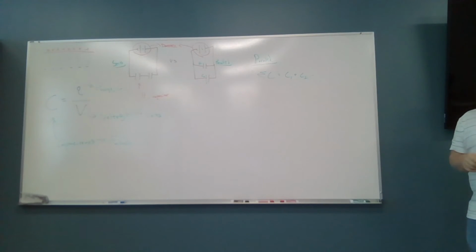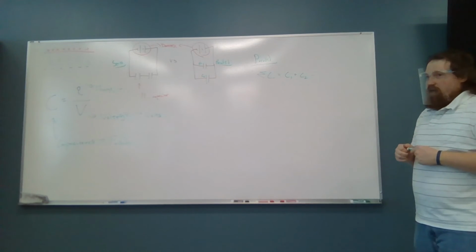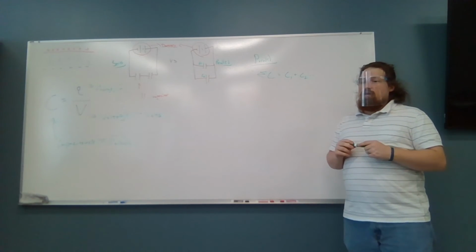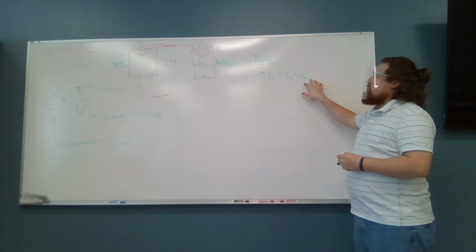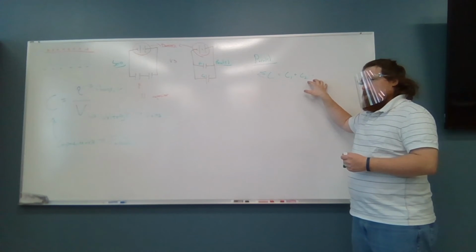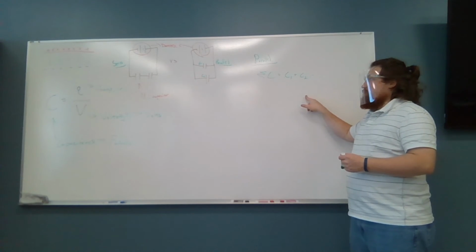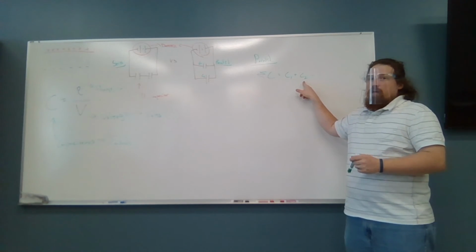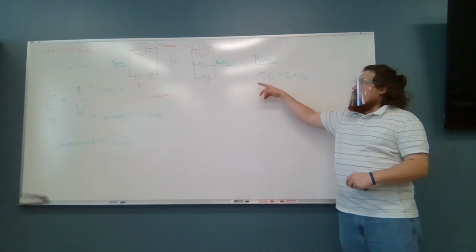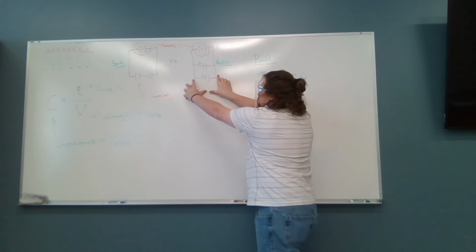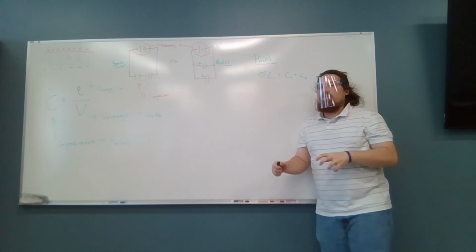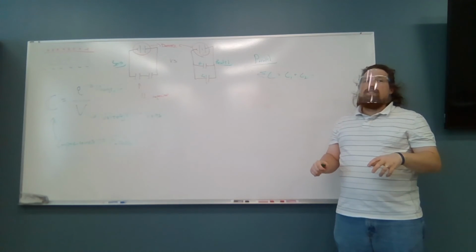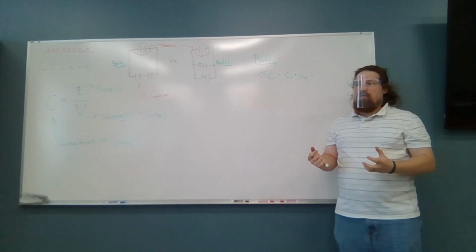Because they were like fractions, right? If you've dealt with resistors in a circuit before, this is how resistors act in series, but capacitors act this way in parallel. So the more capacitors you wire in parallel, the more branches you add here, you drive up the total capacitance of the entire circuit. That whole circuit is able to store more electrons in it.